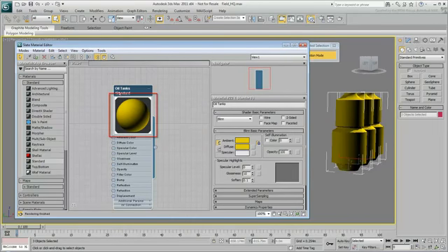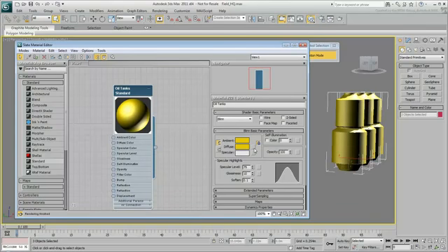It has chamfered corners, which means the material is used in the scene, and any changes you make show in the scene. So if you increase the specular level, both the preview and the oil tanks become shiny. Specular level controls how bright highlights are, while glossiness controls highlight size. In general, shinier materials have smaller highlights. You've created a basic shiny material, but you can add more detail using images or bitmaps. Bitmaps are a very versatile way to add visual detail to scenes. When you use a bitmap to provide an object's color, it's also known as a texture map.